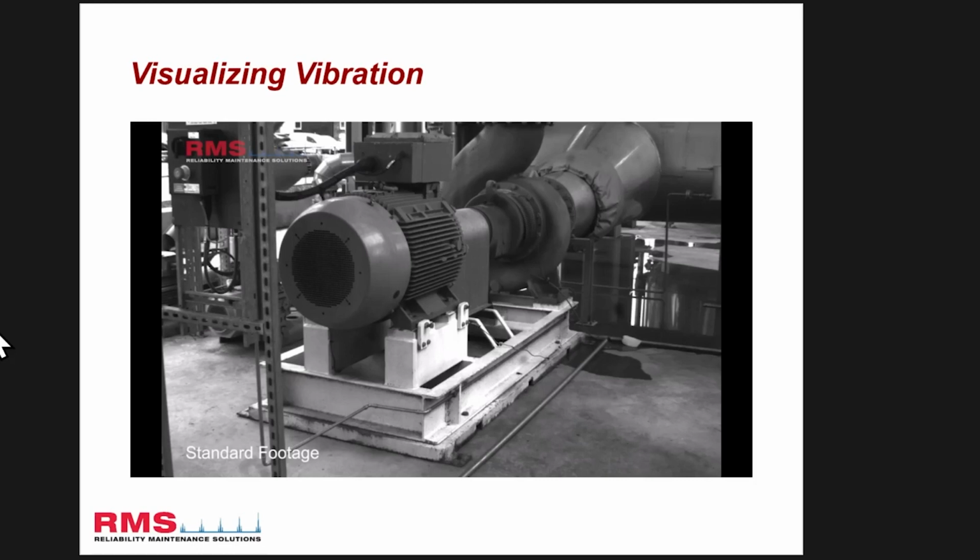Now normally in this situation we would go around, if people are used to this type of technology, with vibration analysis with sensors in triaxial measurement planes on each of the bearing locations of the motor and the pump. We would then analyze that data relevant to a spectrum or a time waveform, complex data plots, to give to a maintenance engineer. Maybe this report can be about 30 pages long. Maintenance engineers today look at this, they don't really understand it, nor should they. They look at it, all I want to know is what's happening with my machine.